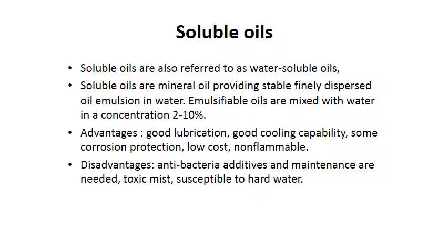Second one is soluble oils. Soluble oil is also referred to as water soluble oil. Soluble oils are mineral oil providing a stable, finely dispersed oil emulsion in water. Oil is mixed with water at a concentration of about 2 to 10%.